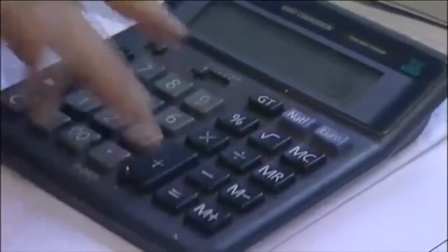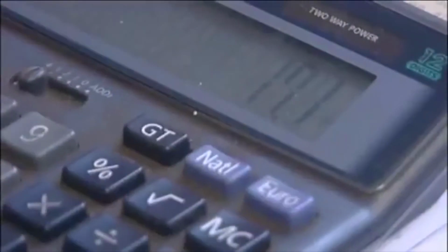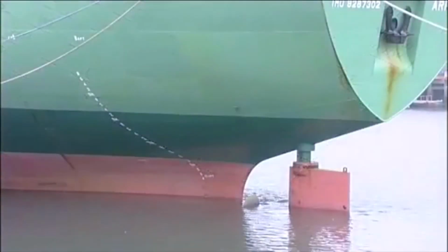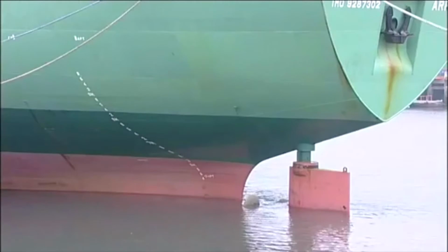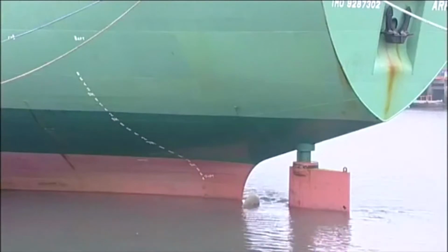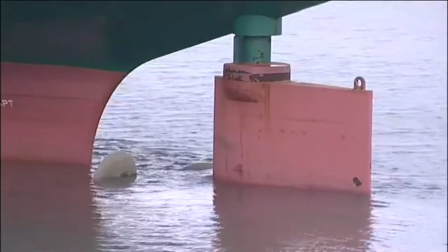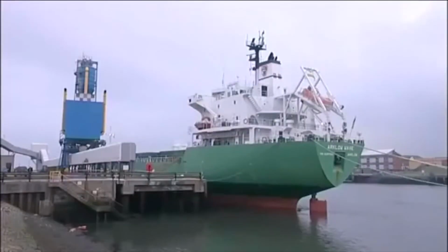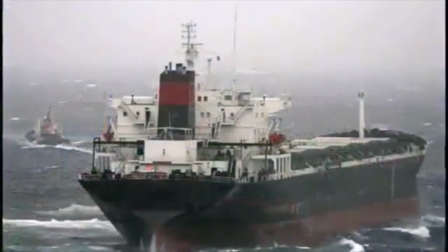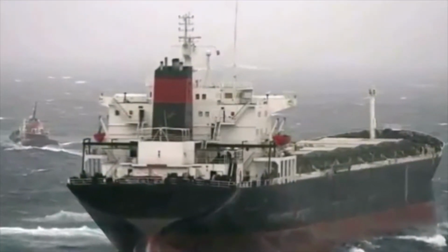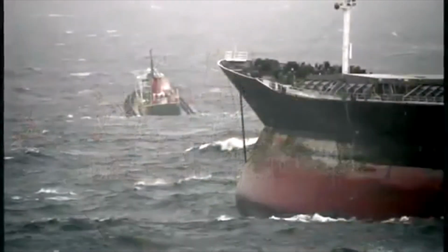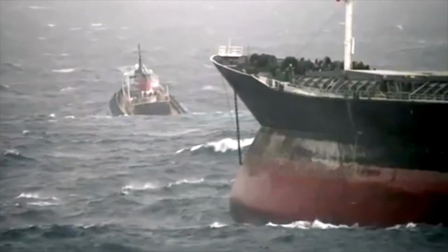And the ship's arrival condition and maneuverability should always be considered. For example, a lightly ballasted ship can become vulnerable during navigation, as both rudder and propeller efficiencies are reduced, and the windage is increased. In these circumstances, the ship's ability to maneuver safely is reduced, particularly in high winds and strong currents.